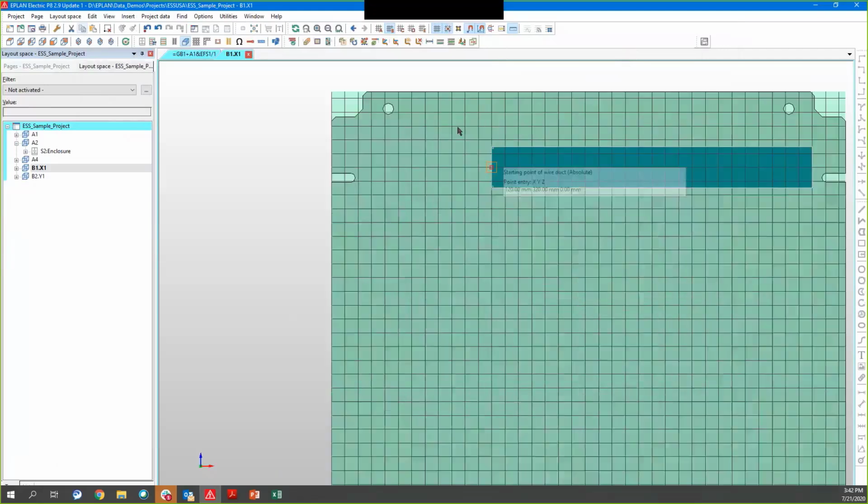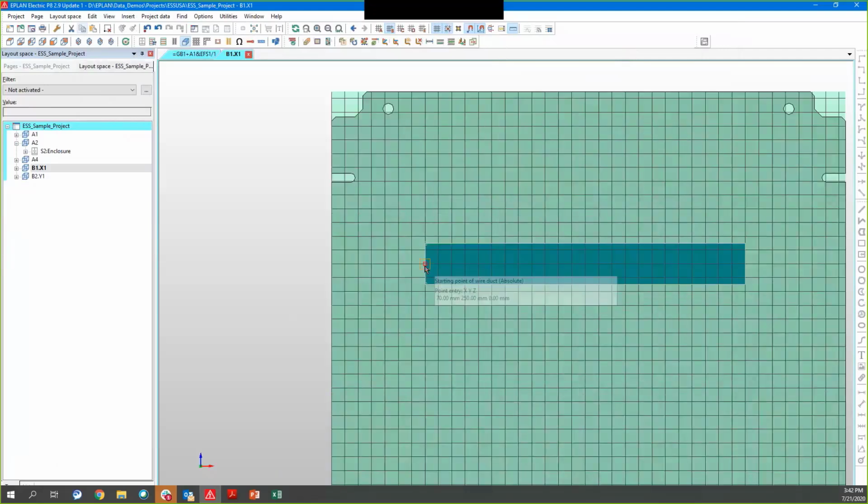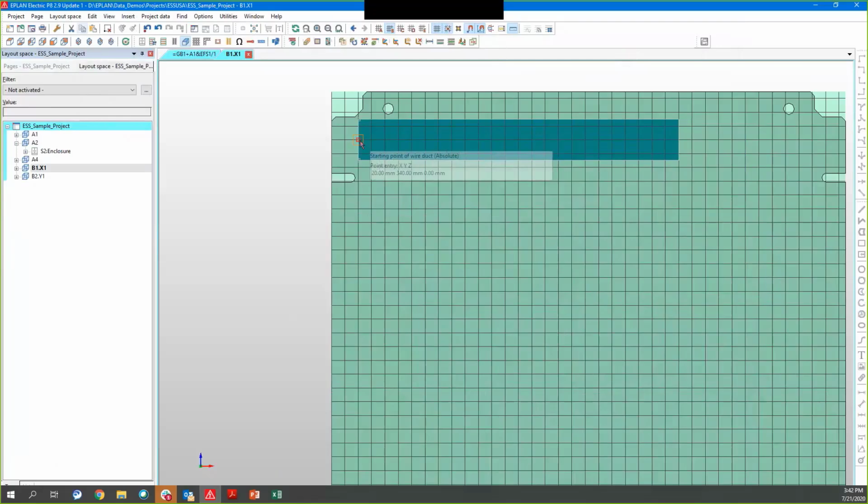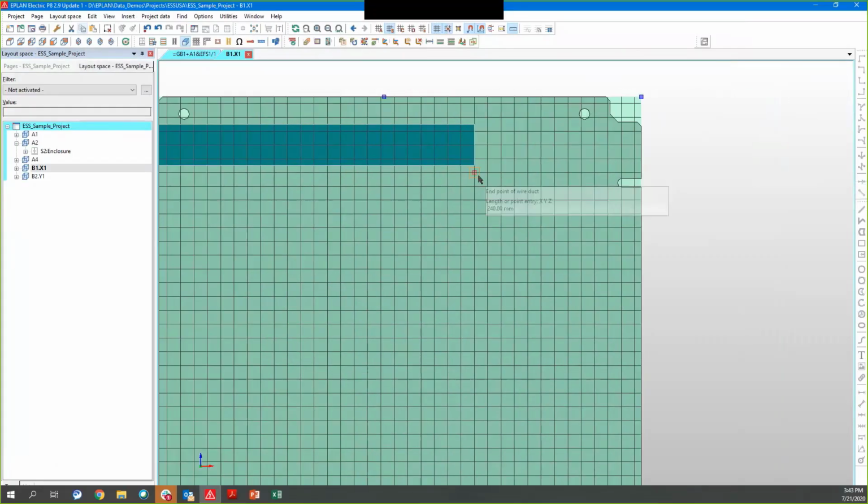And you see instantly it puts the grid up because it knows we want to place this duct work on the grid, or have the option to. So I'm going to select here. These grids are 10mm grids, and you can see probably from the cursor that tells me the position of the point I'm selecting. And then I've just dragged the grid across.